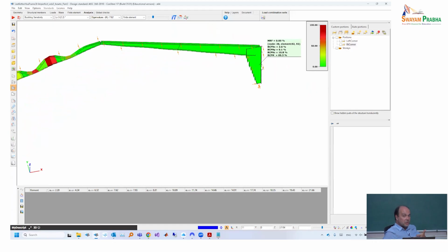So this is a sort of numerical explanation also to that visual feeling that this buckling mode has a certain high relevance for that part which is located here and not elsewhere. And that's the logic used by this buckling sensitivity analysis.